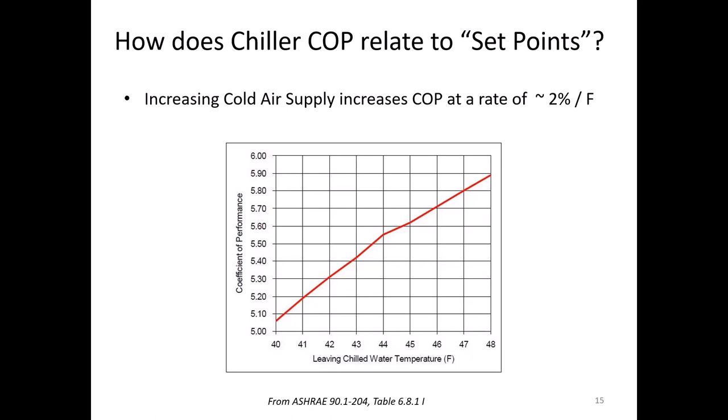And if you run at high supply air temp and therefore high return air temp, the opportunity to use an atmosphere that is nominally ambient temperature increases. In other words, the economizer gets better because the window of opportunity, in terms of temperature, for that economizer to operate widens.